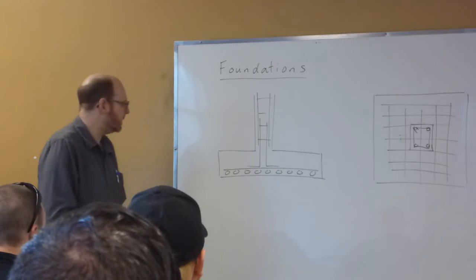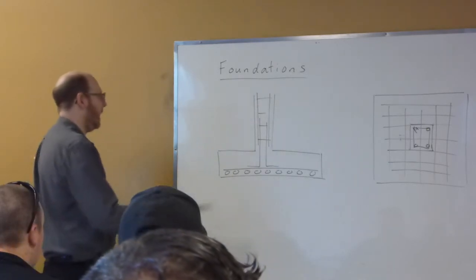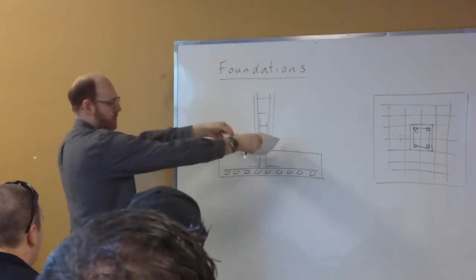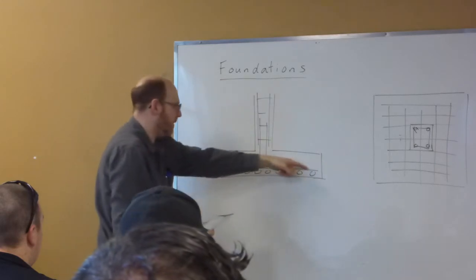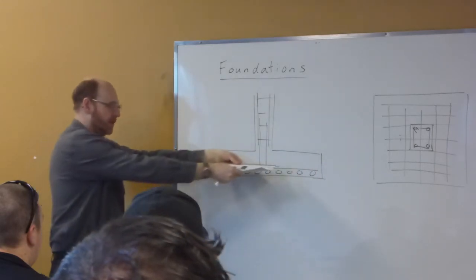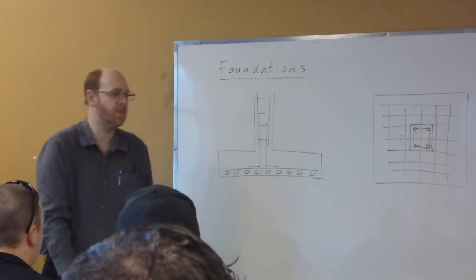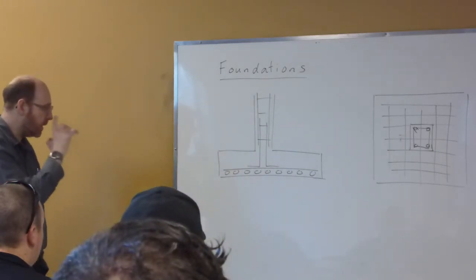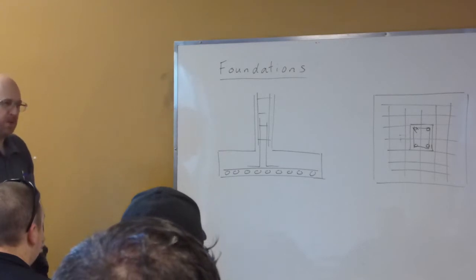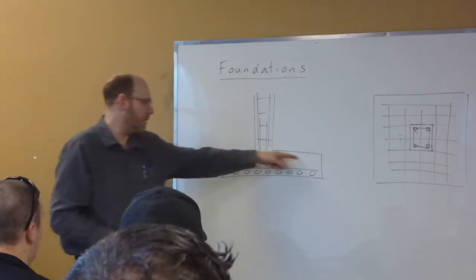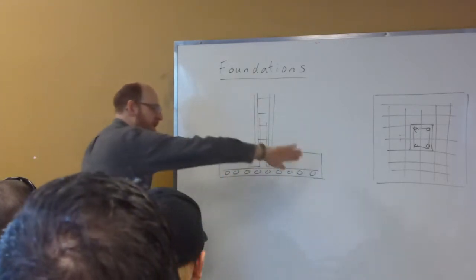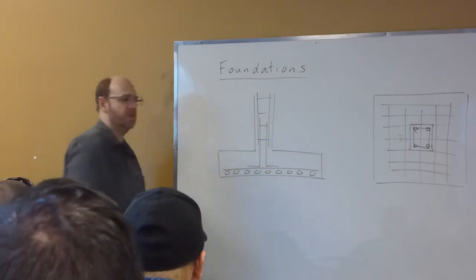So as I take a look at our footing here, right, it's going to bend in this direction. So we have bars going in this direction in order to be able to resist the bending, but it's also going to bend in that direction at the same time. Right, so this is where we get that two-way bending. And you'll notice in our configuration that we don't have any stirrups within there as well, and there's no bars along the top here, right? So as it's bending in this direction, right, our tension zone is at the bottom.